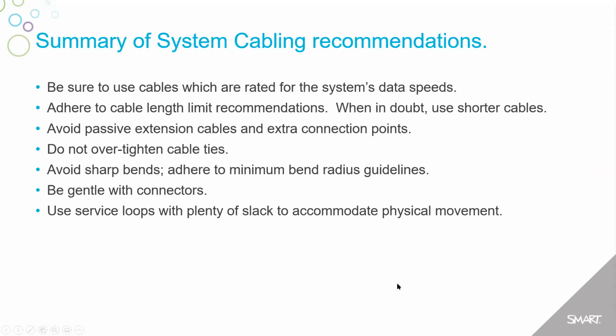So to summarize today's webinar, when using connection cables between your computers and your Smartboard interactive displays, make sure that all of the cables are rated for the system's data speeds. Adhere to length limit recommendations, and if you're unsure of what the length limit recommendations are, use shorter cables where possible. Always avoid passive extension cables and extra connection points.